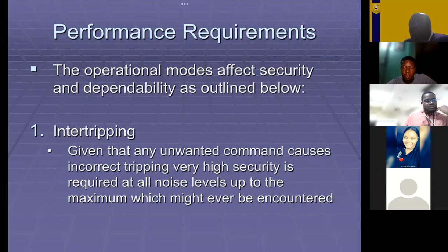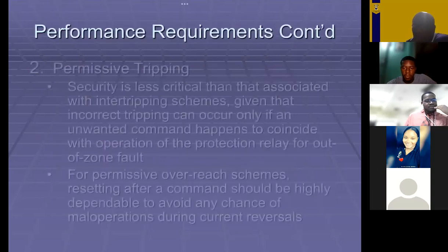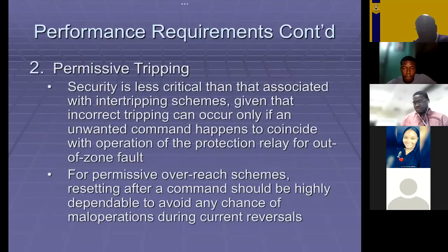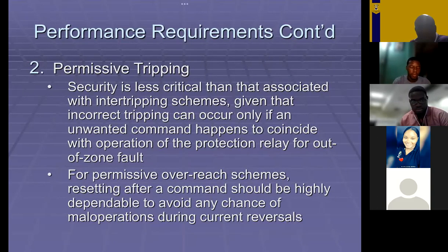Right? Let me give you the others. For permissive, it is less critical than with inter-tripping because you have the supervisory component, so you have that AND function. Whilst security is important, it is not as critical. So it means that you have a little room to play with. Yeah?